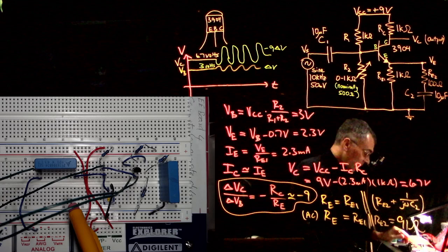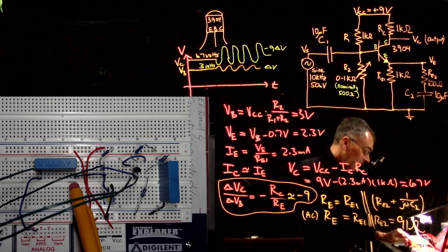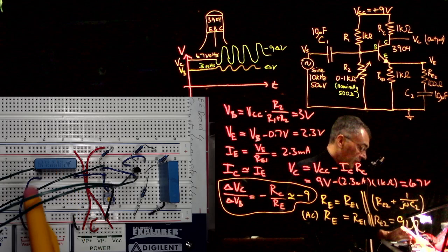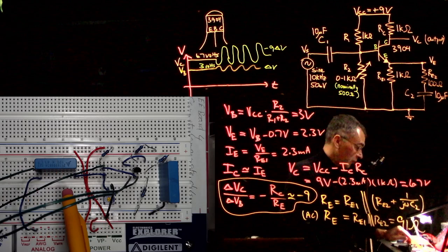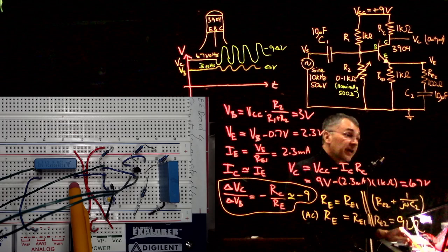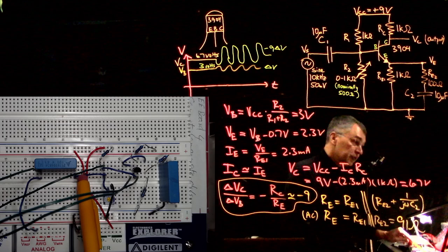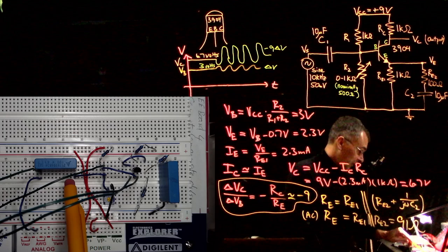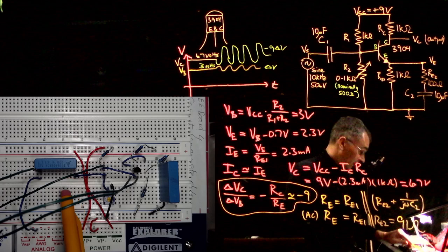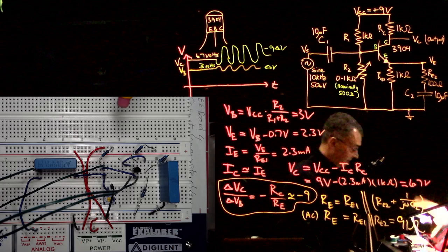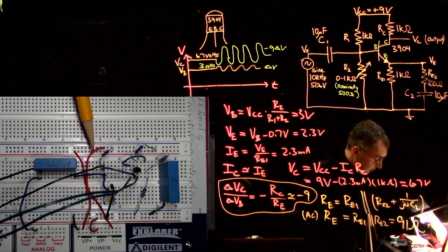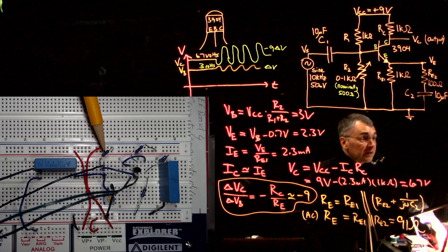And then, let's see, last time I had a little trouble with this 10 microfarad capacitor spanning my power supply wires here, so I just left the right-hand side of that capacitor over here. So I have this little blue wire to jump over from the right-hand side of C1 to where I'm making all my base connections. So here is where I'm making all my base connections in this column right here.